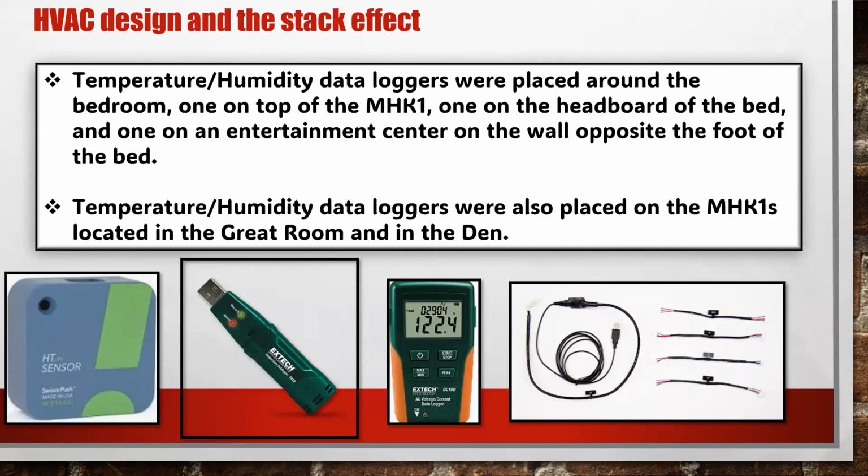Now the best you can find is a poster that shows temperatures pretty much the same in the house on a multi-zone unit, but due to the stack effect, buoyancy of warm heated air, it's always going to be warmer upstairs. It's impossible to have a room upstairs colder than the room downstairs, unless you seal the door off in the room and then open the window. That might be possible. That led to a lot of complaints from homeowners because they saw that poster or they saw this video.